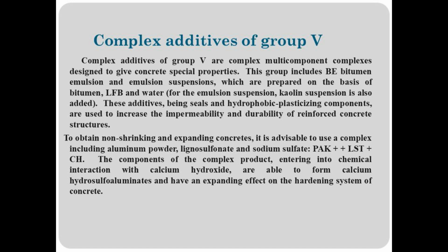For the emulsion suspension, kaolin suspension is also added. These additives, being seals and hydrophobic plasticizing components, are used to increase the impermeability and durability of reinforced concrete structures.